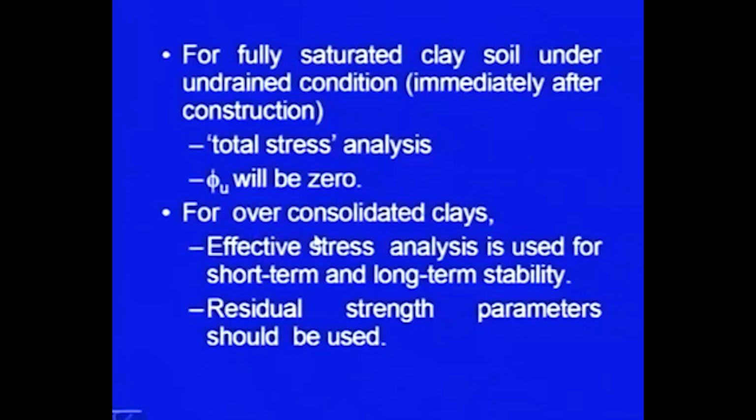If it is over consolidated clay, in that case effective stress analysis is used for short term as well as long term stability. Over consolidated clays are a little bit different case. They have been consolidated more than what they are at present.